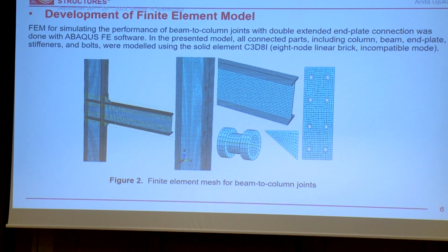To verify the finite element model, I used Abaqus. In the presented model, all the connected parts, including beams, columns, and end plate bolts, were modeled using the solid element C3D8I. One of the key points that I paid attention to is the mesh size, because the accuracy of the results depends on the mesh size, and also the precision of those results.